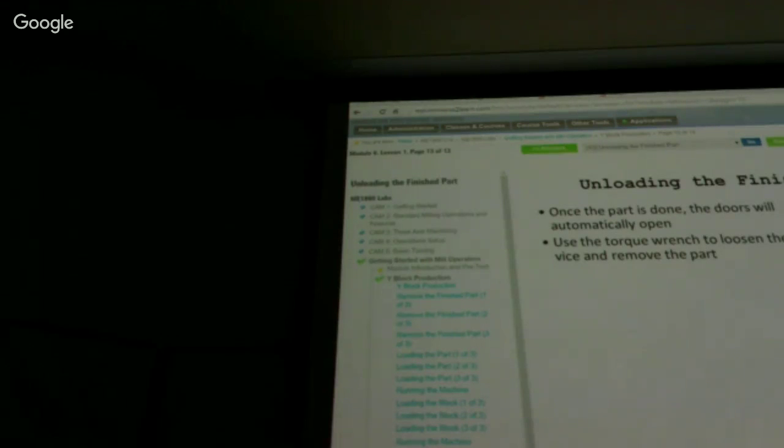The other thing I could do is take an end mill that's got some kind of a radius down there. Now, there's a lot of reasons I like end mills that have a radius right there. Those sharp edges at the corner of an end mill, they break off really easily. There's very high stress concentrations at those points. So if it's rounded, it wears out more slowly and more predictably. So I could take an end mill that's got a radius down here, and I could cut here, and here, and here, and here.